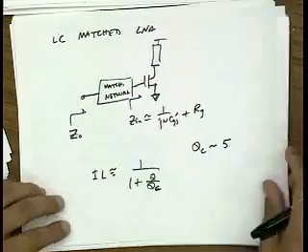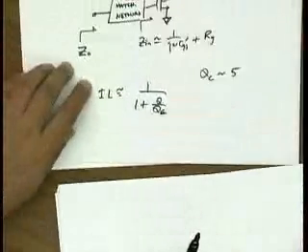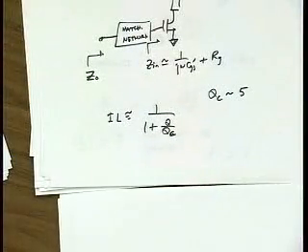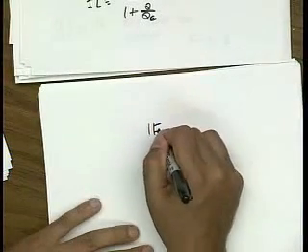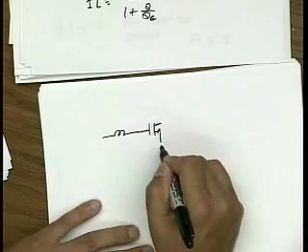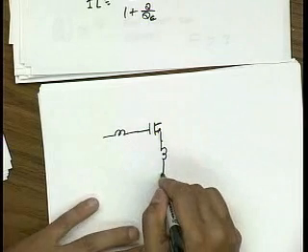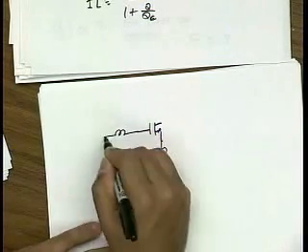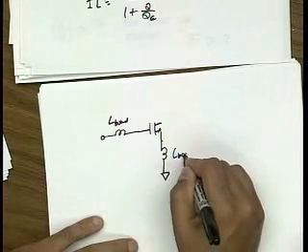Okay. Well, somebody at some point figured out a nice tricky way of matching a device like this, and it was actually a very practical way. So the idea is that if I actually interface my amplifier to the external world, I'm going to get bond wires. And bond wires, depending on the path, will generate inductances. So I can make an equivalent circuit that looks like this. So this is a bond wire inductance, this is a bond wire inductance.